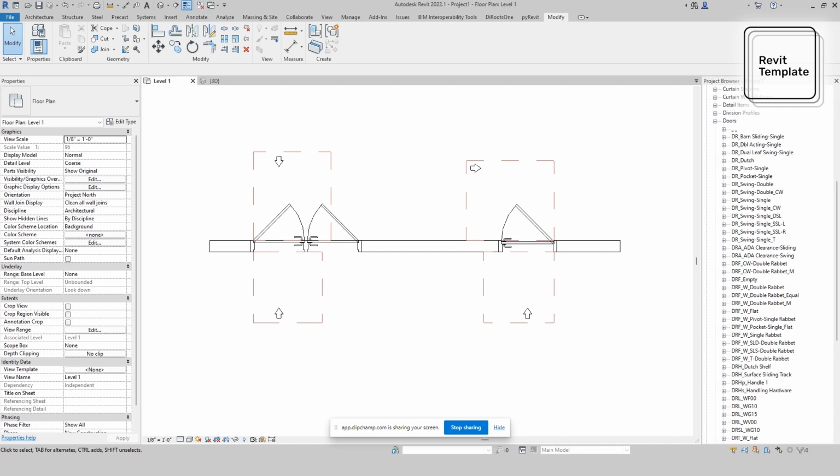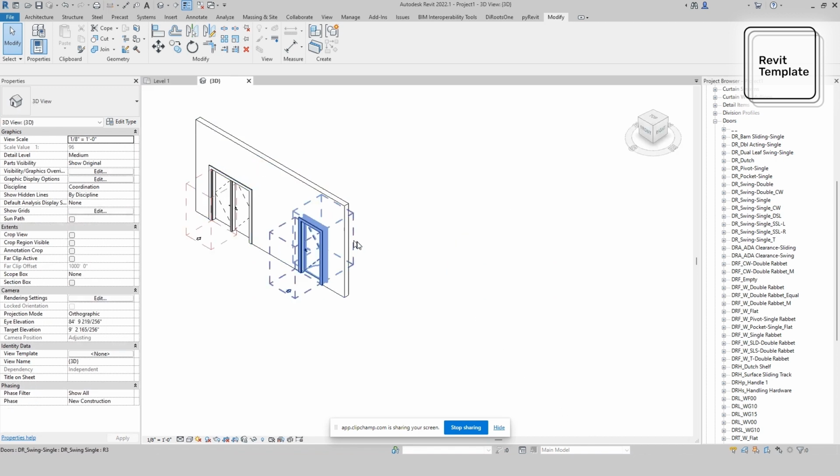In this video, we will discuss door clearances and egress calculation parameters for the Ultimate Door collection. This collection comes with accessible code-compliant approach annotations. These annotations comply and adjust to meet US ADA 2010 and ICC A117.1 accessibility code. Each door opening, aside from the specialty doors, integrates clearance lines that are visible both in 2D and in 3D.